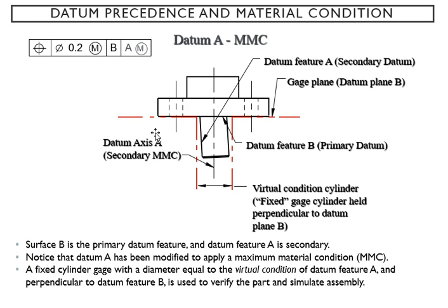I believe at this point you should be able to get it. The only thing that is new is right here: the secondary has the MMC. So meaning this thing that you're drawing has got to be inside your MMC, which has got to be bigger than your actual part. That's all you need to know.